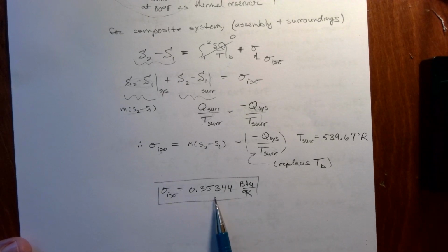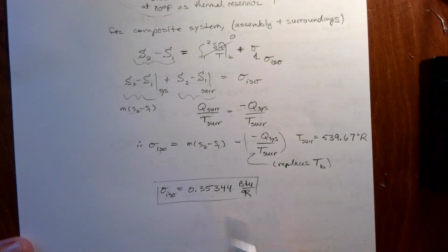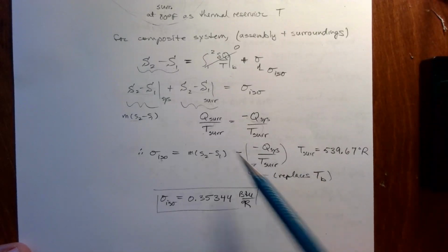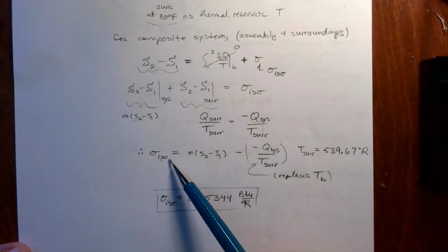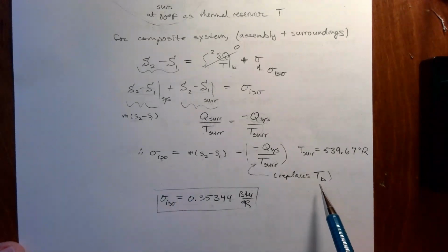And so there is entropy being generated or produced. So this is a physically possible, irreversible system. Let's say theoretically possible, irreversible system. So there's sigma isolated. I actually prefer that we check the second law with sigma ISO, because it's not common to actually have a boundary temperature.